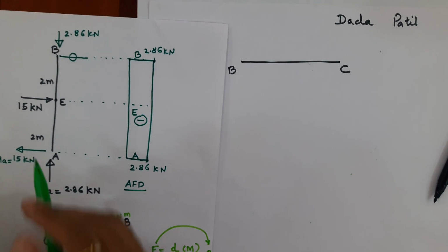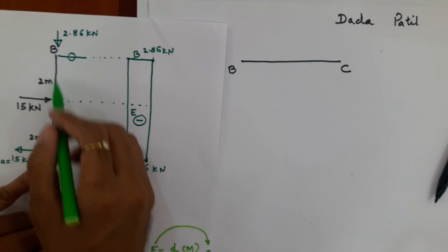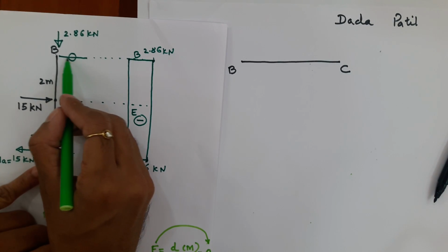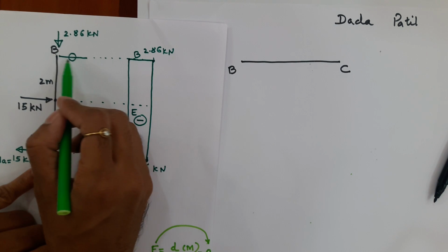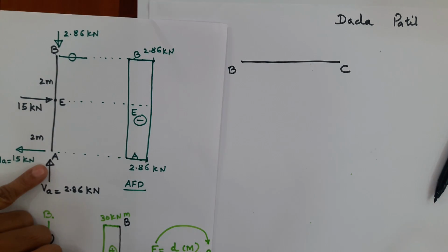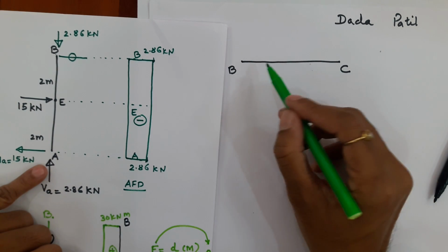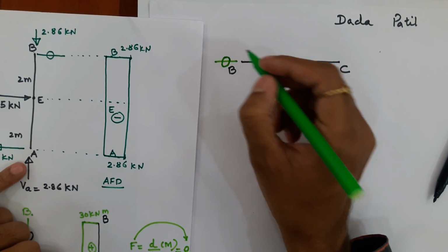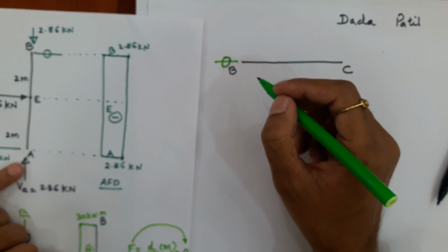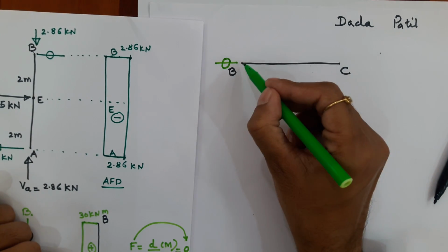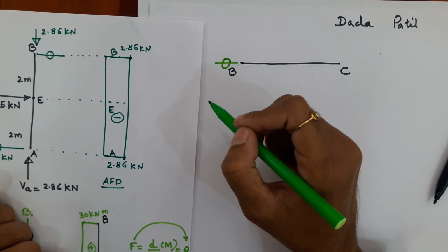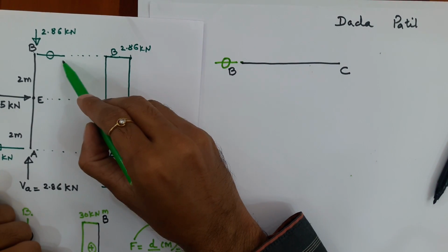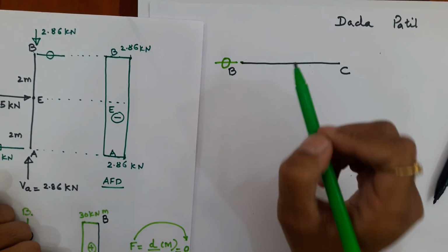Now if you compare or if you take diagram AB, now I know that this was 0. So again here this must be 0 because in engineering mechanics you have learned that for the whole structure to be in equilibrium, each particle must be under equilibrium. So when this reactive force was 0, this must be 0.